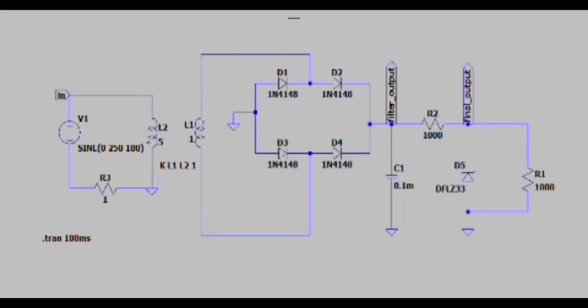Thus, the capacitor is used to filter the positive DC voltage. The capacitor can help in reducing the variation of the output voltage. When the voltage is supplied, the capacitor will be charged until the input voltage peaks. When the input voltage starts decreasing, the capacitor will discharge gradually and return stored energy. The capacitor will be charged again when the input voltage increases and the voltage supply is larger than the capacitor voltage. So the fluctuation in the rectified voltage can be reduced. However, there is still a small amount of fluctuation, which is also known as a ripple.